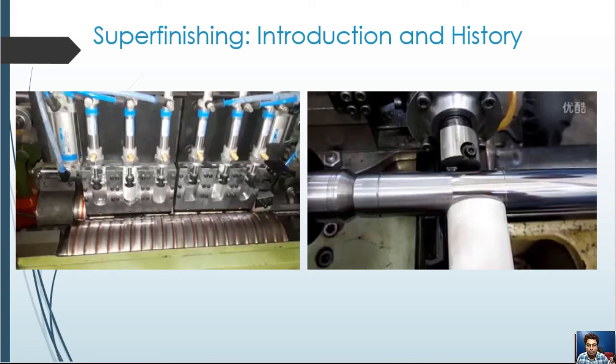In the subsequent super finishing process, the loaded stone contacts the rough surface of the next workpiece to initiate self-dressing or auto sharpening, as we have spoken about in grinding processes in lecture 1, providing the stone with sharp cutting edges, and the three phases described are repeated. In comparison with honing and lapping, super finishing exhibits higher finishing efficiency.